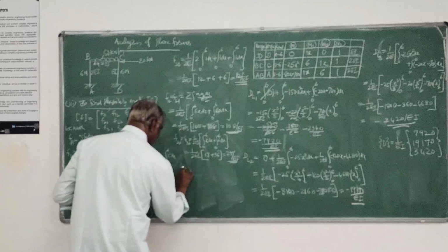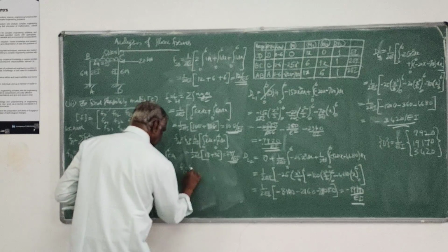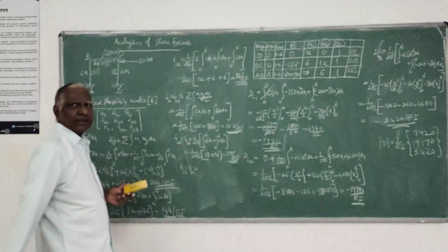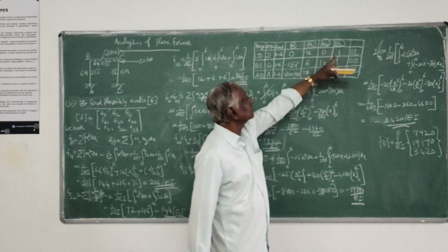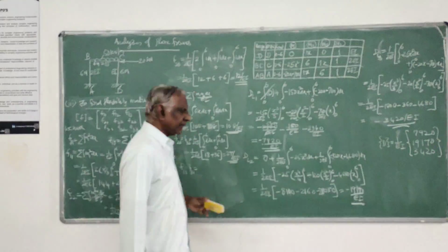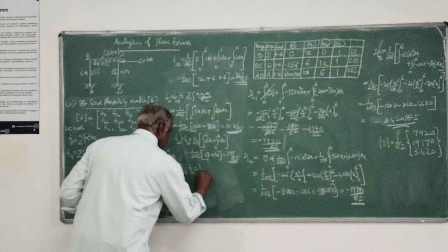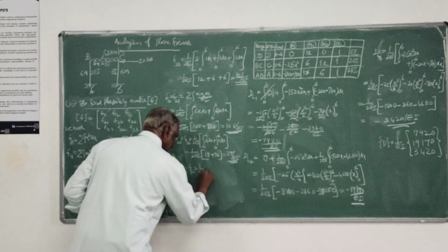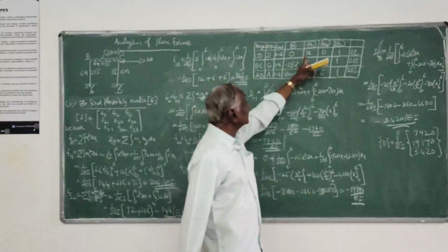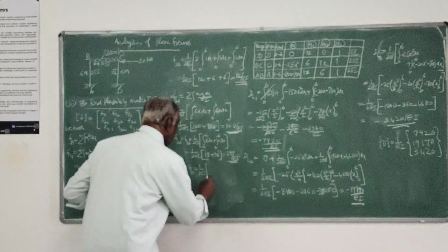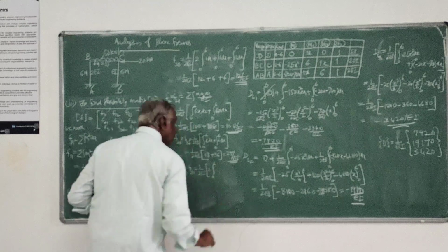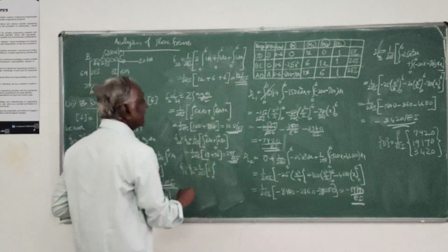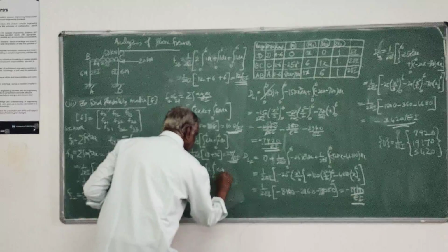Then lastly, F13, F31 are equal. F13, that is this into this. First one, all are coming into picture, that is 1 over 2EI, I will take it outside as usual. 2 into x. So this I have to multiply by 2. 2 into integral 0 to 6 of x into x dx, correct?